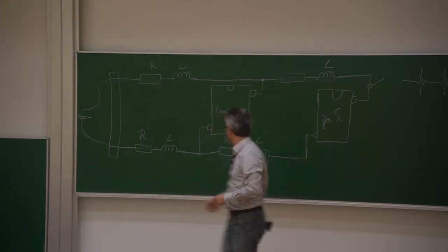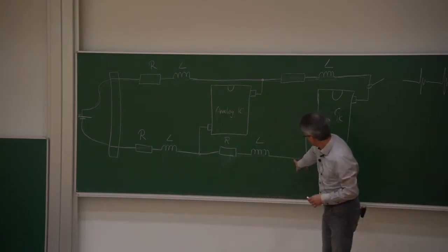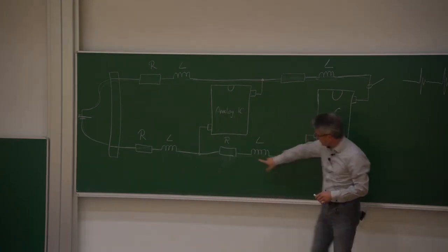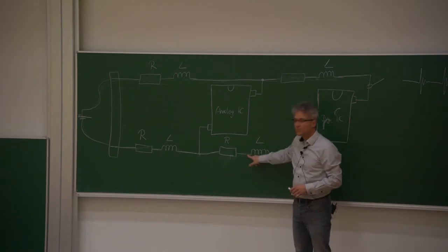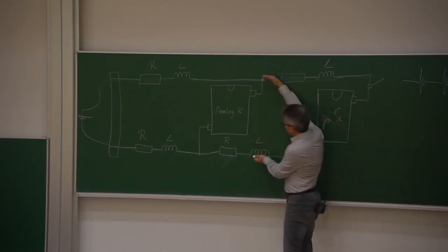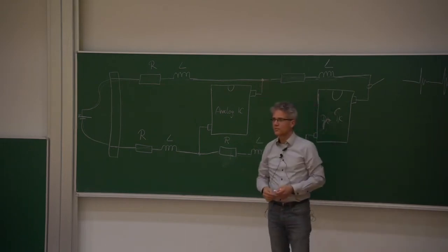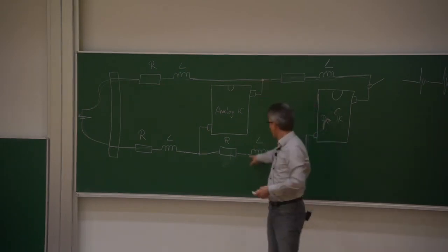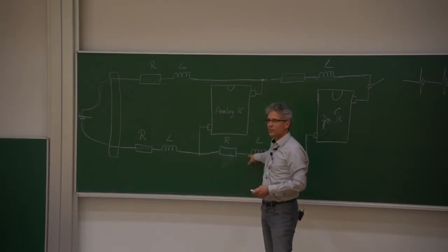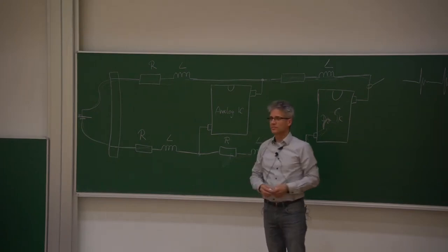Because I hope you agree that there is a difference in this parasitic inductance, if the loop is that big or if I'm placing the traces very close together. So this general rule, it's 1 centimeter, so therefore it's 7 nanohenry, is not always true because it depends on how big the loop is.